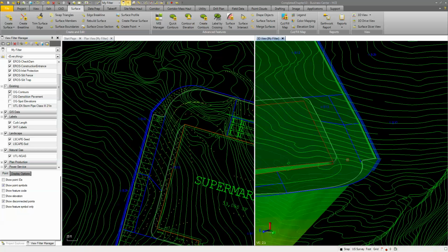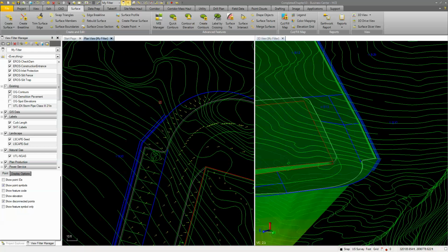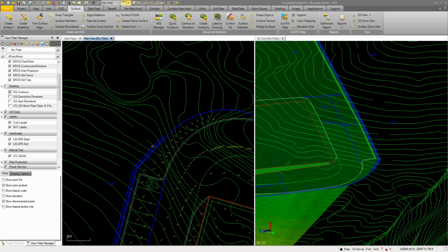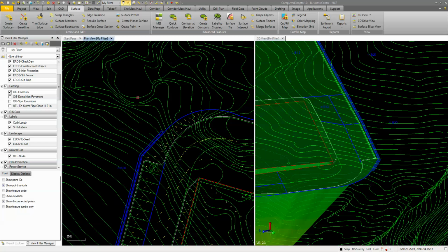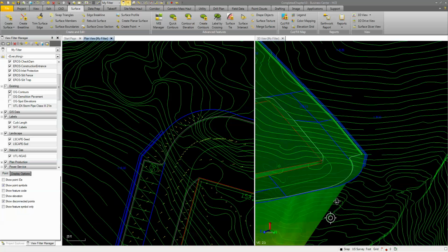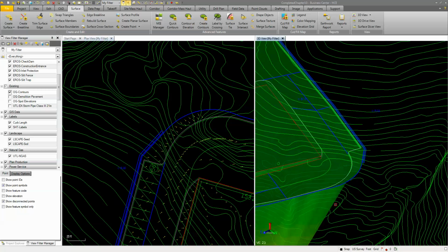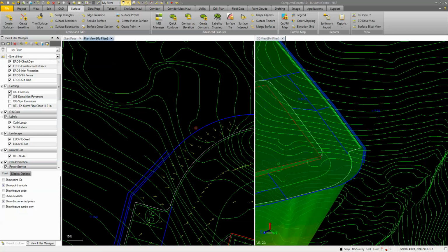In the contours you can see that we've got a bit of a swale through here. We have a little bit of a plateau right here. And what we want to do is ditch this out. We want to change this ditch so that it slopes out into this area and dumps over there. So again, maybe we come in and put a little detention pond or some type of filter in here, but that's something we can deal with later. Right now we're just going to drain it out to this area here. So I'm going to use this contour as my elevation.